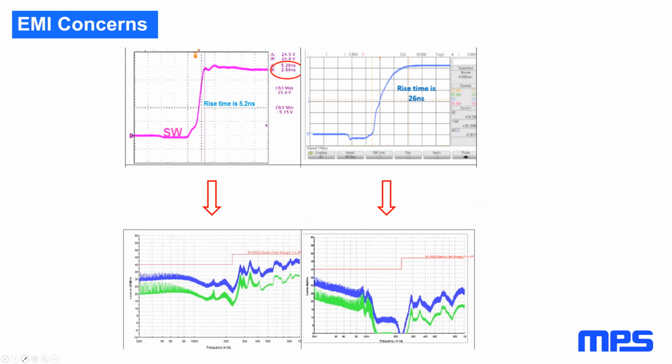Another big problem that comes from switching fast is that it generates EMI, electromagnetic interference. Almost all electronic products need to meet regulatory agency requirements about how much EMI they generate. EMI causes problems with communication systems as the radiated radio frequency energy causes interference. EMI can also interfere with other nearby circuitry just by coupling noise into sensitive nodes.